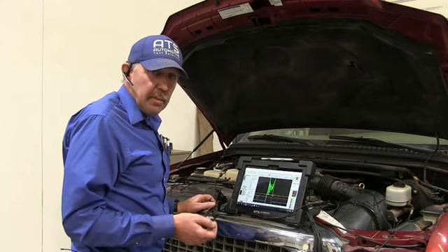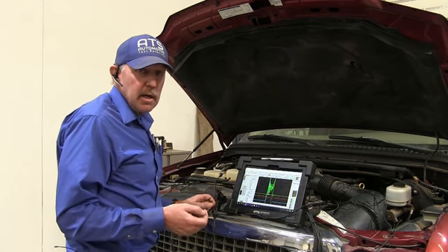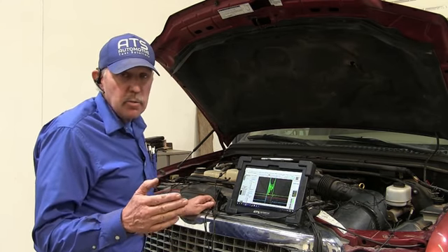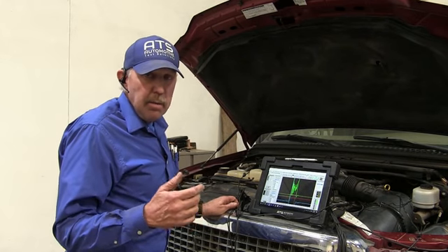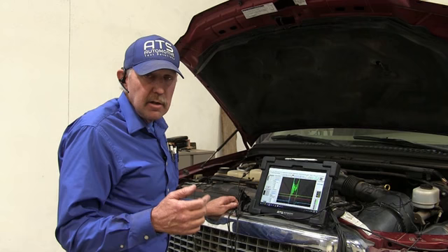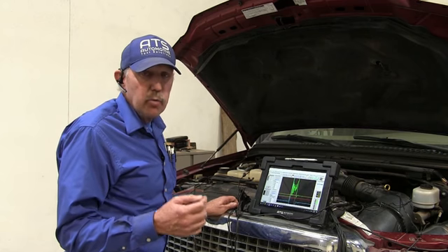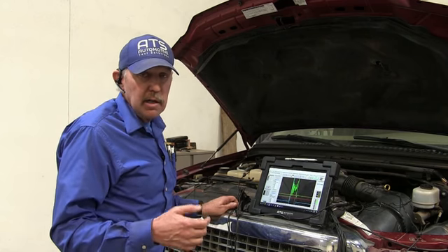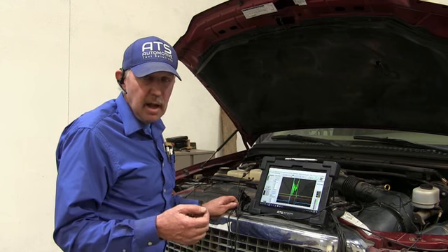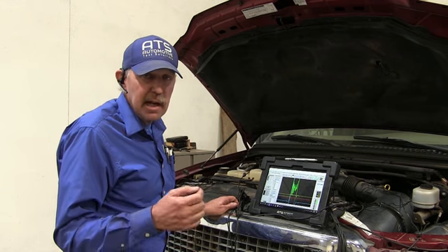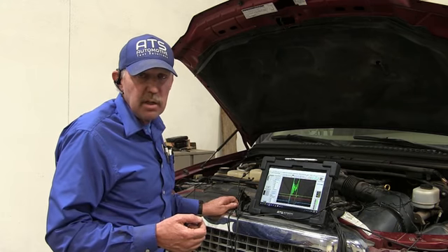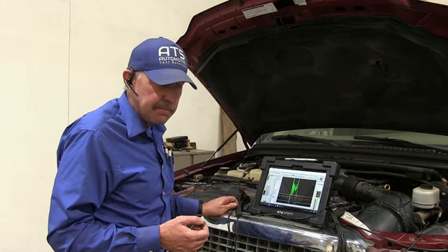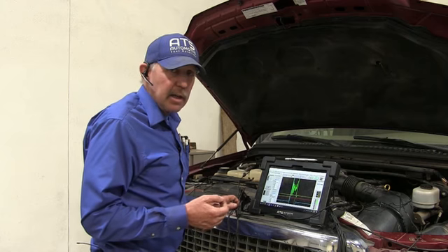So that coil on number 9 is going to have to be replaced. Now the next problem that you've got is we need to probably put the coil and the plug in 9, but we probably have a problem because to arc through a coil, it has to have really had some hard hits. Like maybe that cylinder is lean. We're going to have to figure that out, but before I can do that, I need to put a coil in here, and then we'll run these same tests and I'll show you what the difference is when the coil's not bad. So let me get that coil in here.